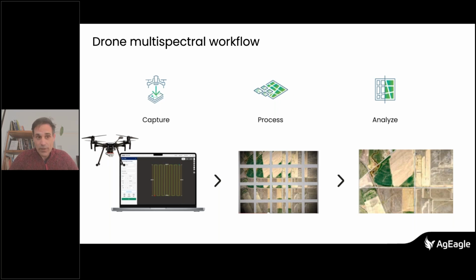The alternative would be to have a fixed shutter time, right? But then if you want to work like this, you need to know the optimal shutter time for the illumination at that moment in time, right? We can explain later on in the configuration of the camera how you can set this. Also important is to always fly on the outside of the limits of your terrain. So if you mark your terrain, you need to fly really around it as well, so that the inside pixels are also covered from all sides, okay?